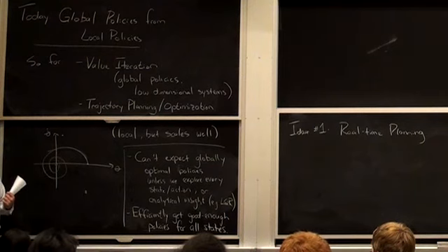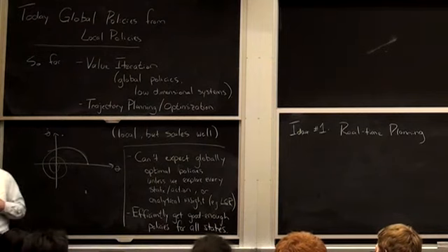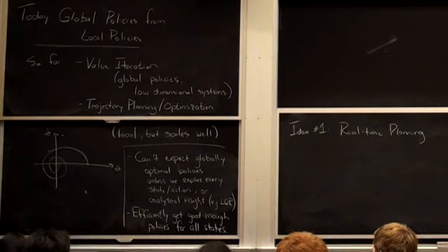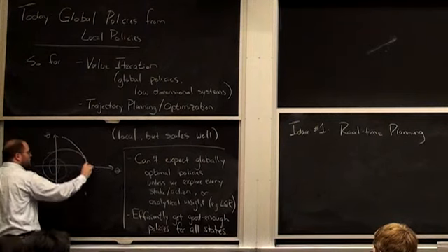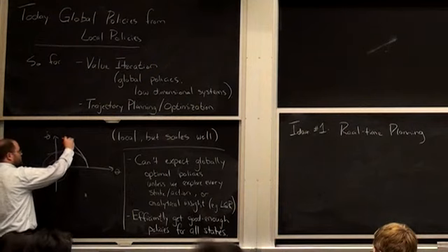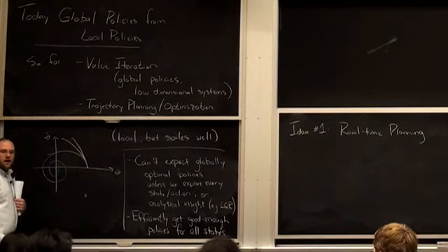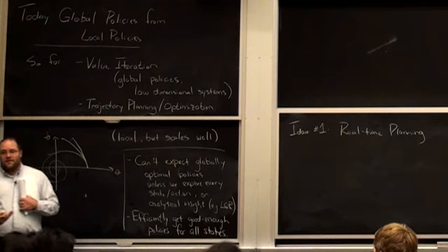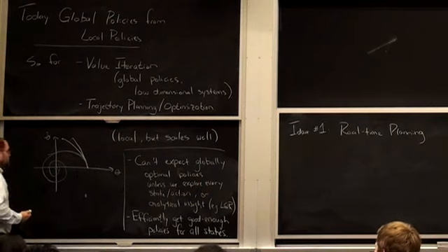I've got a real-time execution task here. Like every, let's say, 100th of a second, my control system's asking me for a decision about what to do. But if I can plan fast enough, and I find myself in this state, then you could just plan again, right? Every time you find yourself in a new state, plan a trajectory that's going to get me to the goal. If I'm executing this trajectory and I get pushed off by a disturbance, no problem. Every step I'm just planning a trajectory to the goal. If we teach the course again in 5 years, maybe that's the only answer. I don't know. If you can plan fast enough, that really is a beautiful answer.